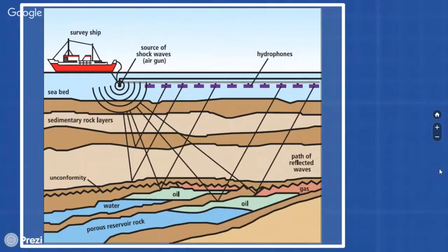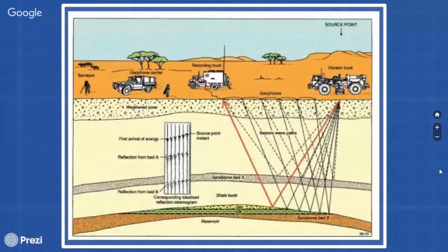Inland seismic surveys tend to be large entities, requiring hundreds of tons of equipment and employing anywhere from a few hundred to a few thousand people, deployed over vast areas for many months. There are a number of options available for a controlled seismic source in a land survey, and particularly common choices are vibroseis and dynamite. Vibroseis is a non-impulsive source that is cheap and efficient but requires flat ground to operate on, making its use more difficult in undeveloped areas.